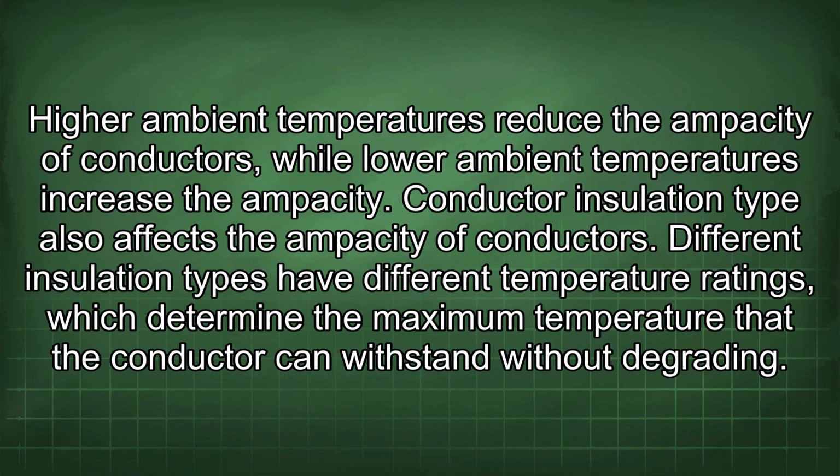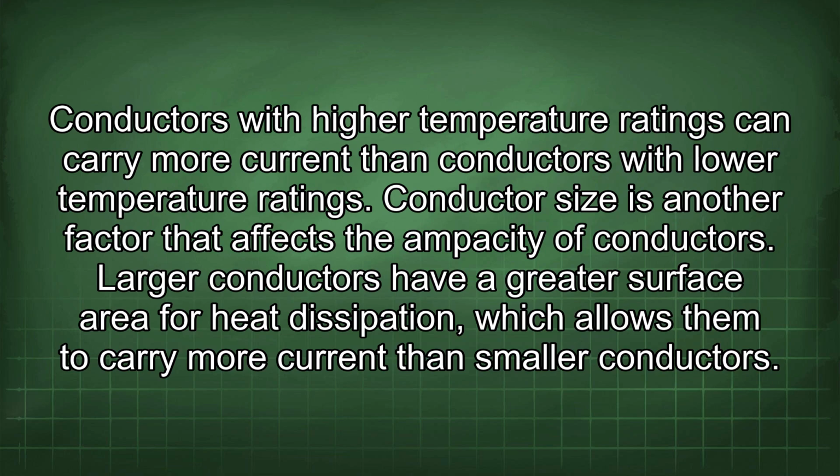Conductor insulation type also affects the ampacity of conductors. Different insulation types have different temperature ratings, which determine the maximum temperature that the conductor can withstand without degrading. Conductors with higher temperature ratings can carry more current than conductors with lower temperature ratings.